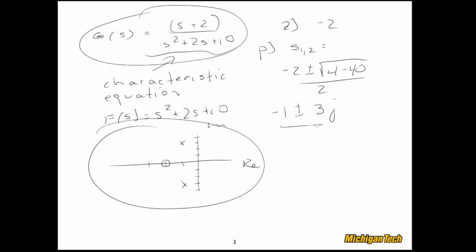Okay, so we have several different ways to represent a dynamic system. We have the time domain, we have pole zero diagrams, and also transfer functions. Now let's start talking about the response. To do that, we need to introduce the initial value theorem, IVT, and the final value theorem, FVT. What these do is give us a way of working with the system in the Laplace domain, a transfer function, and determining characteristics of the response of the system in the time domain.